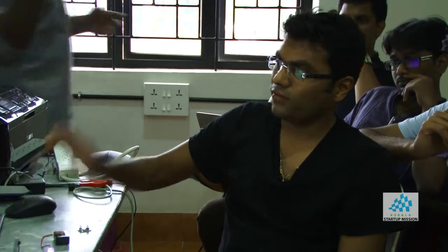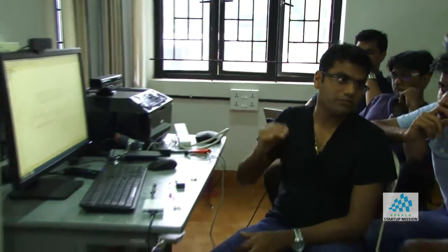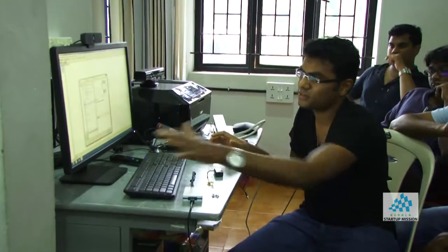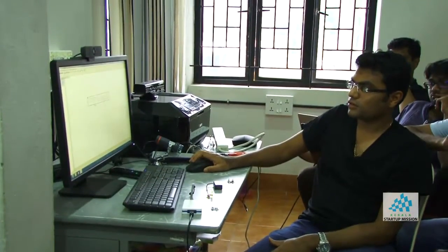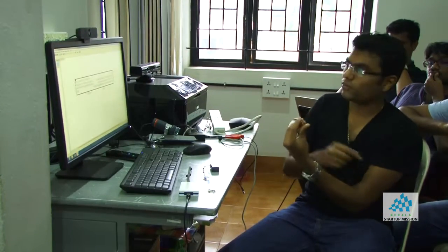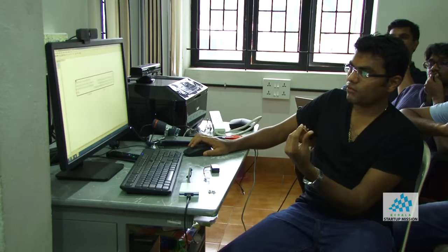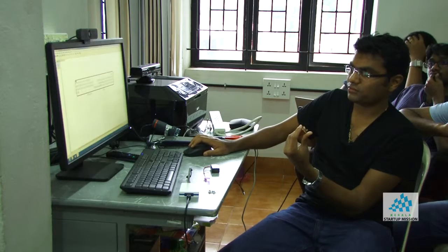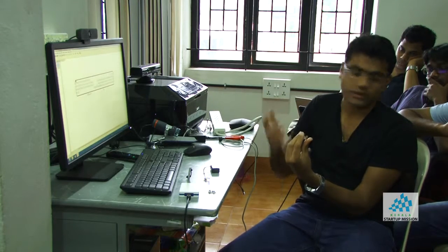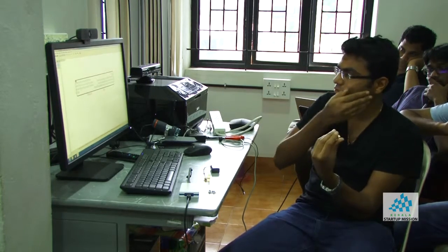Click OK. So here you have the ATtiny44. Once I click it, one copy is placed but it's still attached to the cursor. This is useful if you have multiple resistors, so you can just keep on clicking. But I don't want it, so I'll press the escape button and cancel it. Here you can see there are 8 pins, corresponding to the 8 pins of your microcontroller. One of the pins is the reset pin. All of this you can read in the data sheet. If you Google ATtiny45 data sheet, you will see all the information.